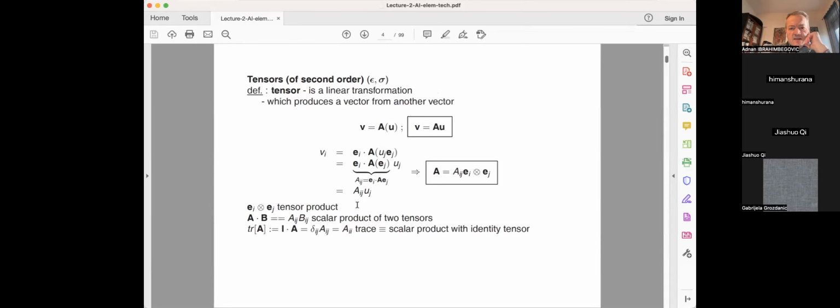So basically, the idea is that once we have designed this notation, we are able to reproduce the equations for 1D in a direct manner. Only you will have bold-faced letters instead of thin letters. Now I try to follow the convention where tensors are capital letters and vectors are lowercase letters. However, epsilon and sigma, the stress and strain tensors, will be bold-faced, but they are actually second-order tensors and they're lowercase, because big sigma would be like a summation sign, and big epsilon would be like the letter E.